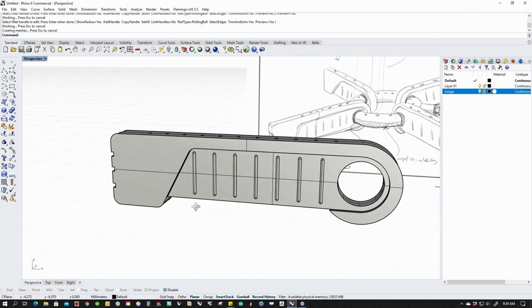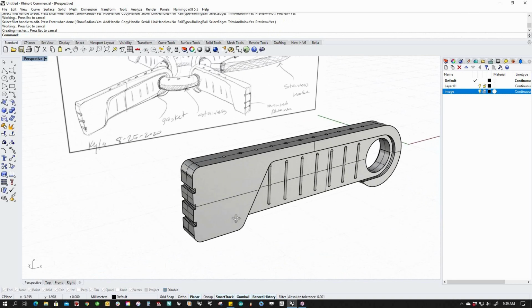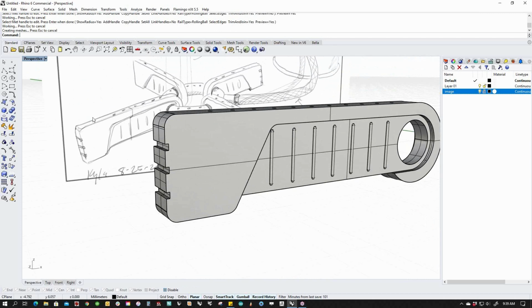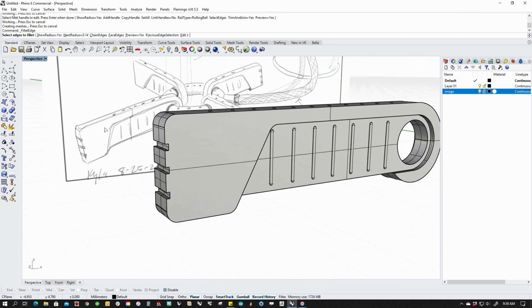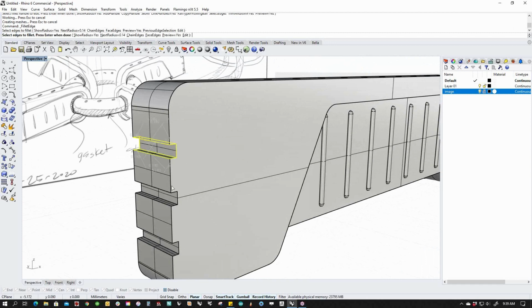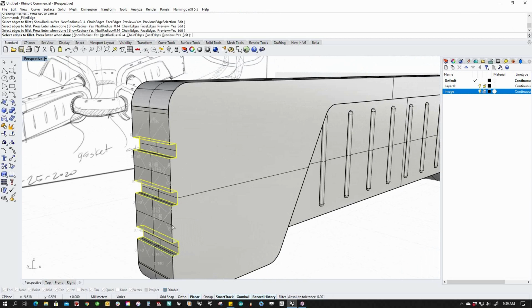Now the second pass is going to be the smaller fillets, and we're going to do those with a much smaller fillet because we want to get all of this stuff, right? So I'm going to run fillets again, and I'm going to start picking these guys, and these, and I'm just selecting, and I'm picking this and this and this.